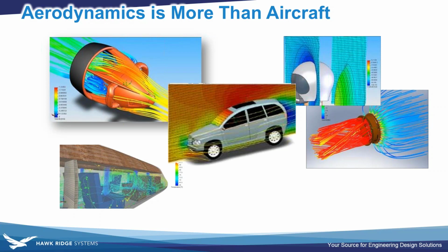And if you're not familiar, you can even take the results from SOLIDWORKS Flow Simulation, specifically the pressure results from that airflow, and those can be directly exported to the stress analysis in SOLIDWORKS Simulation or other programs, so that you can get an accurate stress simulation of the real pressure contours and not just assuming some kind of uniform load.